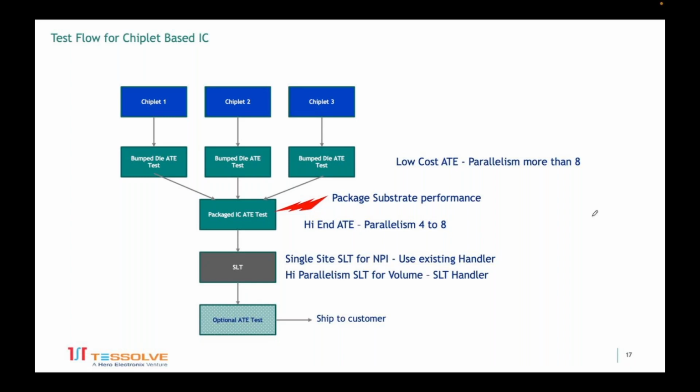Of course, if the reticle size of your mask is much smaller, then you could still consider monolithic. But when you go to chiplet, test is a huge area to determine the ultimate yield at package level and its performance. So various aspects come into the picture, which is what I am trying to cover in this flow.